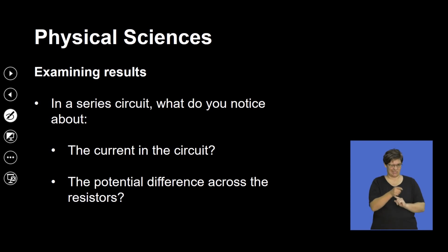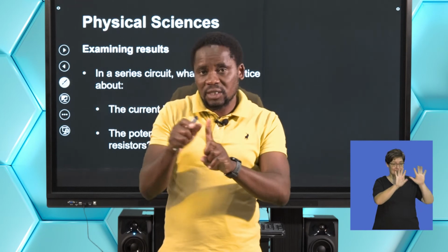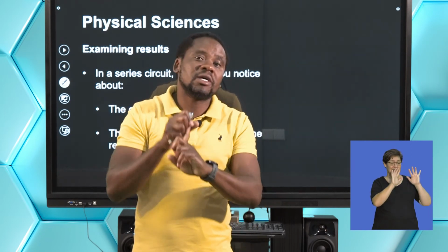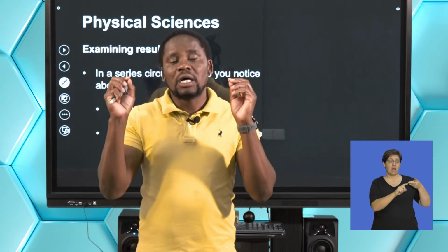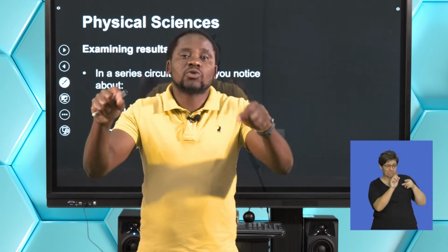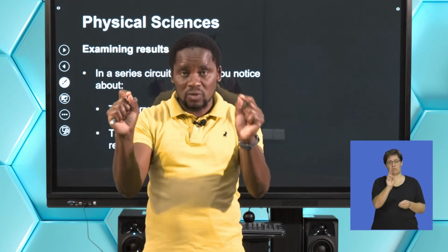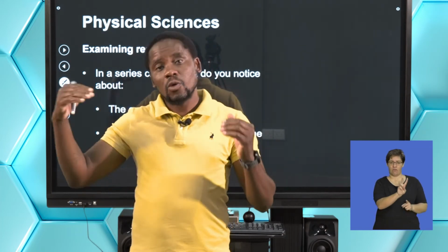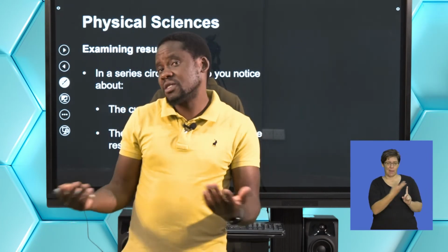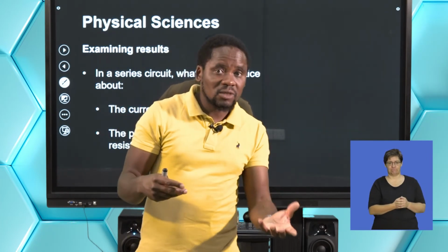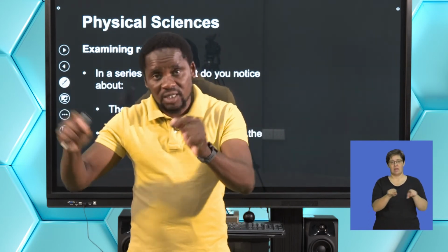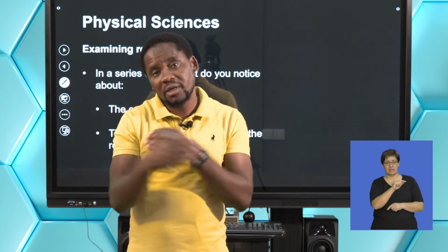What we've changed is the number of resistors in series. We have 2 resistors. We started with one of magnitude 10 ohms, which is R1. We managed to measure the resistance of that particular resistor, which is equal to the total resistance in the circuit, by measuring the voltage across R1, and then knowing how much current, we can use the equation: resistance of R1 equals voltage across R1 divided by the current that passes through R1.